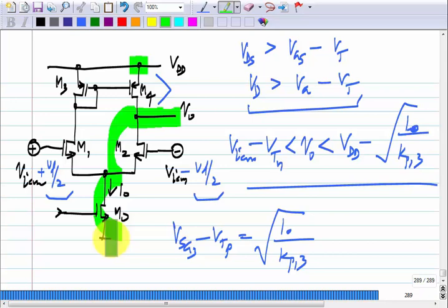So, now if you make a circuit using this op amp, first of all, in any circuit, even without knowing all of this, you can go and evaluate the swing limits from scratch, right. You can evaluate the incremental voltages, total VGS, VDS and ID of every device and find out when any device goes into saturation or cutoff. But again, as we make more and more complicated circuits, we have to make macro models for a collection of transistors. Otherwise, it becomes too painful, right. You do not go into the transistor level for, let us say, a 1000 transistor circuit, you will build it up hierarchically. So, for an op amp we have some swing limits.